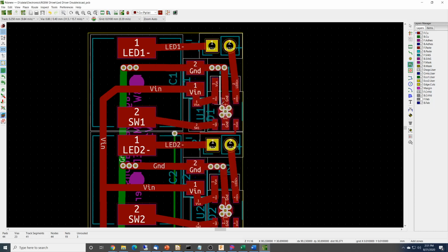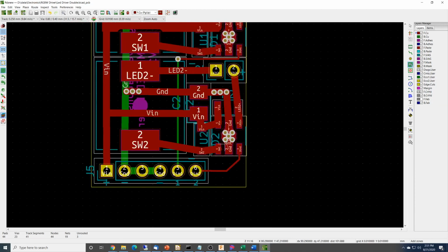Okay, holding down Control again to keep it square. I want to come across, okay, click there. I want to come across and get that VN all the way across over here and then double click. And what you noticed is not only did I get the copper pour, but it very nicely kept clearance here and clearance here and clearance here. So that just gives me kind of a nicer view, and it's also nicer in that I don't know which of these pins is using the most power. So having them all tied together just makes things nice.